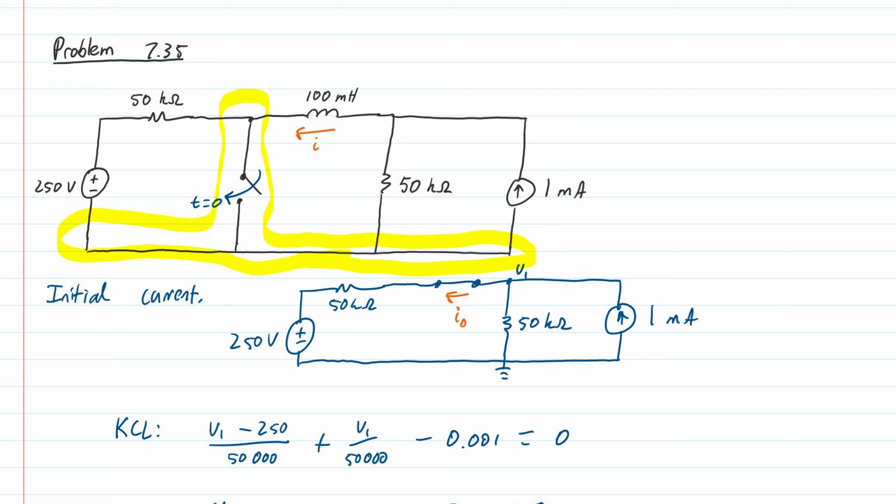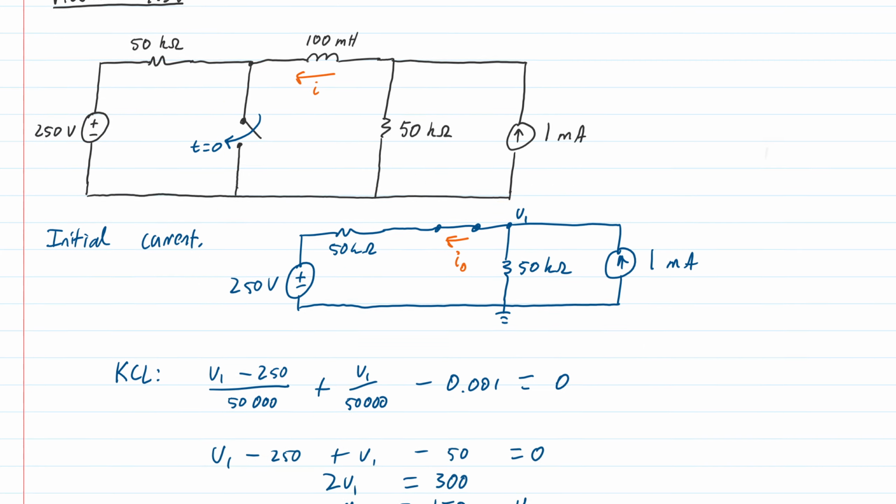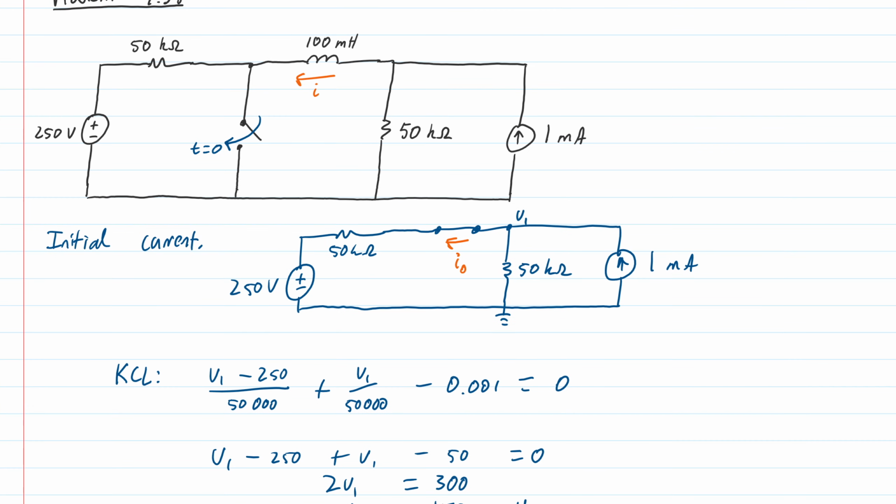So basically it has the effect of completely isolating the voltage source on the left-hand side, right? This voltage source out here will be completely isolated from the circuit. It will have no impact at all. And so I can redraw the circuit in a fairly simple way.